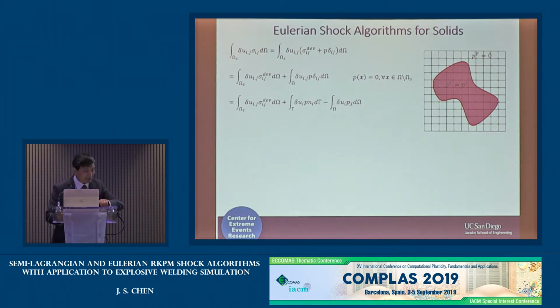So the last thing is that, well, if I now wanted to unify this with the shock propagation in the air and in the solid, can I unify them by just making everything Eulerian? If everything is in the Eulerian description, even for the solid, then with the Eulerian shock formulation that I just mentioned, it will just work. Just directly plug into this approach, right? So I have a solid here, and then I have an Eulerian grid.